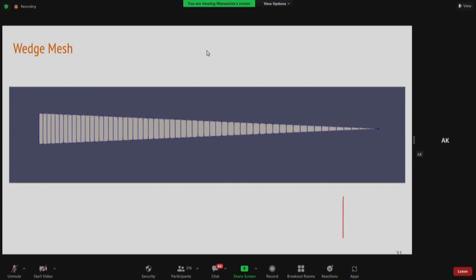When you're simulating the flow through a pipe, at the inlet generally we prescribe the velocity and the pressure is prescribed as del P equal to 0, and at the outlet we say del U is equal to 0 and P is equal to some P outlet. Is there any reason why it is like that generally? I mean, why don't we prescribe the pressure at the inlet instead?